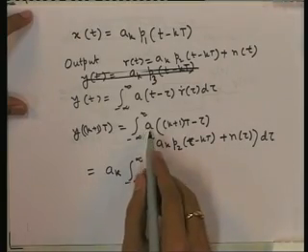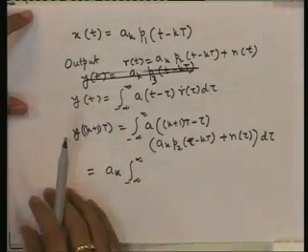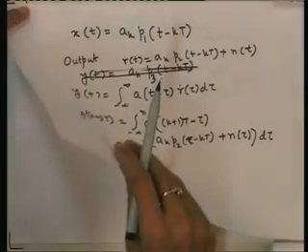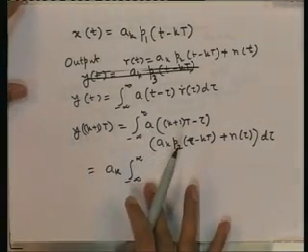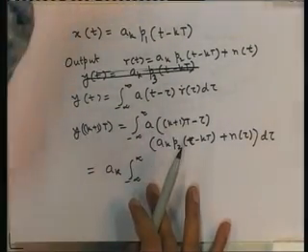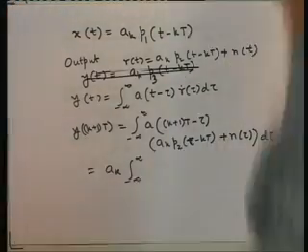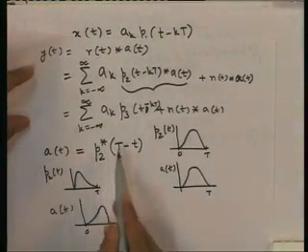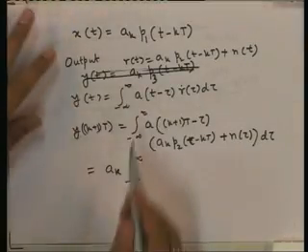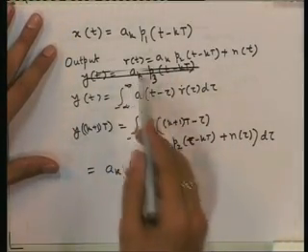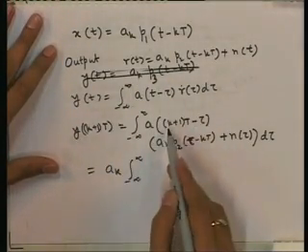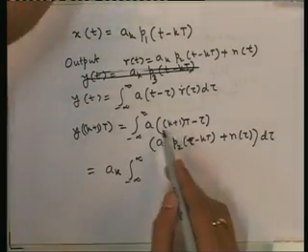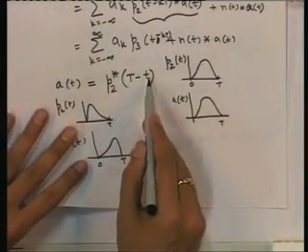Now you can see that we are taking the matched filter. For the matched filter, we have a(t) equal to p2 star of (T minus t). So we replace a by that; this whole thing will be put in place of t.